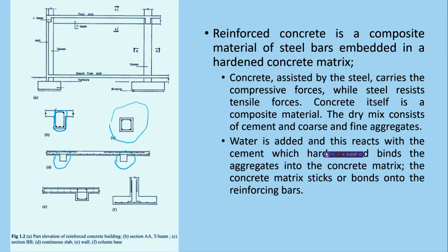So a slab is different from a beam in terms of the layout, sorry, how you are going to put the bar. Because the bars are in directions that cross each other like this, for example. So you will place bars maybe like this, and then you will place bars like this. Okay, or you use BRC. Okay, so it will become like a mesh.